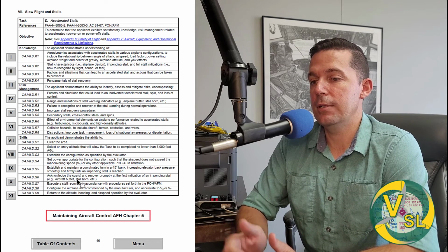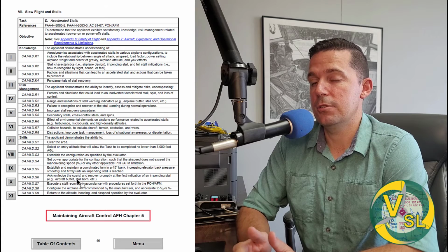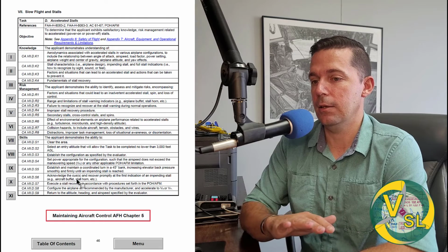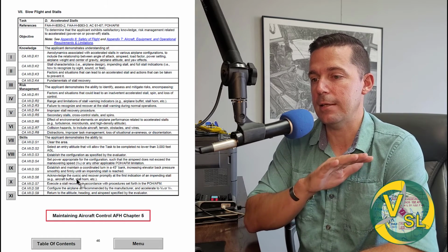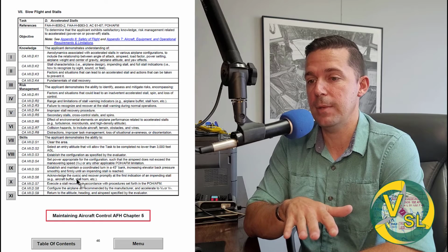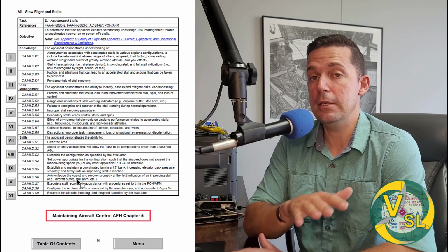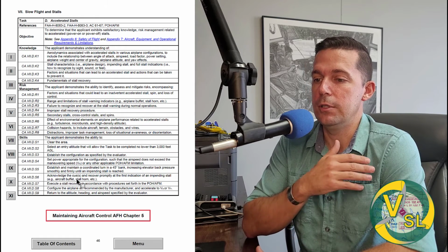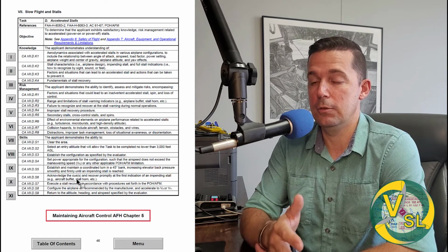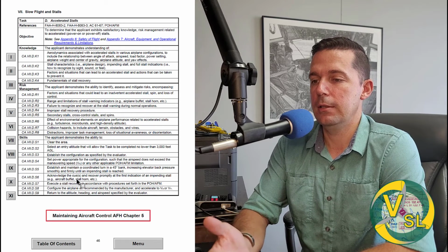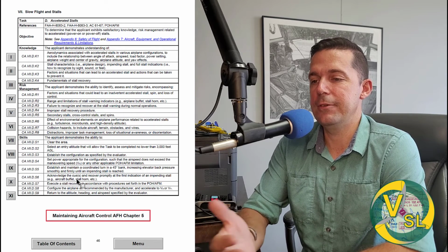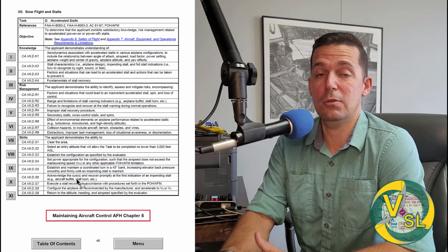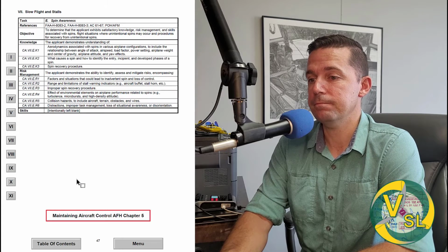And we're not going to take this to a full stall. We're going to take this just to the first indication. So it's going to be kind of a rapid onset, and we'll hear the stall horn or see the stall light or feel the buffet, and we're going to immediately release back pressure, and we'll immediately recover. As soon as you release back pressure, your stall speed drops. You get further away from stall speed, and you lose that stall indication. So it's a pretty quick maneuver. If you've never done it before, it's basically like trying to do steep turns with a low power setting, and that'll induce an accelerated stall.